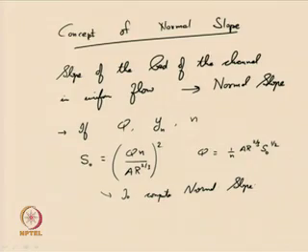Why this normal slope is discussed is that normal slope is available only for uniform flow. If you vary the slope of the channel for the same depth, whichever normal depth you have been initially using for the uniform flow, and just vary the bed slope, you may see that at a certain situation the flow will just become critical.